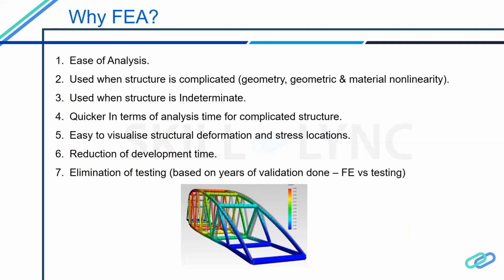A few people might have in mind why we are using this for the cabin interior business. Using an FEA tool will simplify our job, because the cabin interiors, the galleys or monuments, are all indeterminate structures. They've got a lot of support. For example, a typical galley will have 5 to 6 lower attachments. So the structure is totally indeterminate.